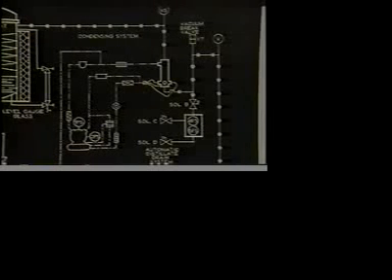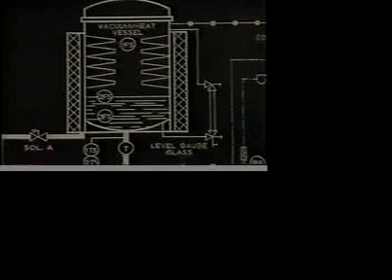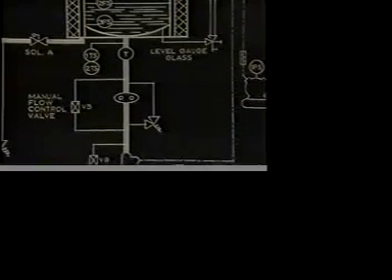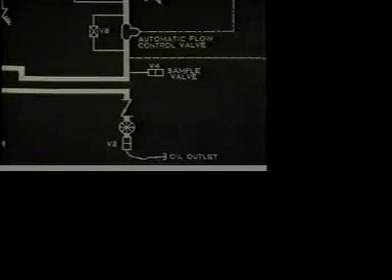Before we arrive at the vacuum pump, the vapors go through a condenser system. And in this condenser system, we are primarily interested in condensing water vapors so that these water vapors can be discharged through a drain as shown right here. We did indicate that the clean lube oil goes to the bottom of this vessel. From there, through an automatic flow control valve, back to the oil outlet pipe or oil outlet hose, and from there it returns to the lube oil reservoir that we're planning to purify.